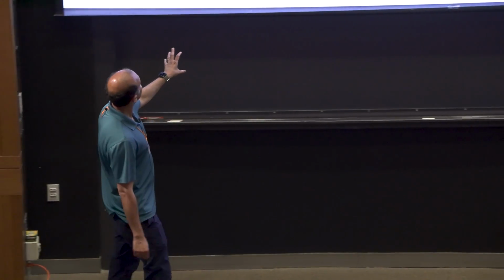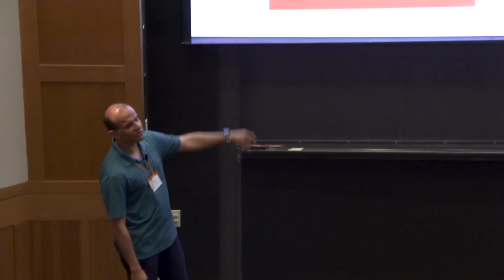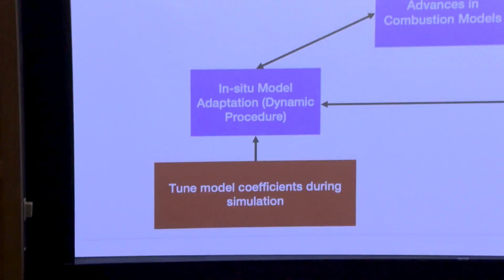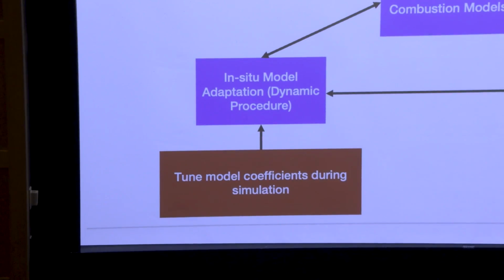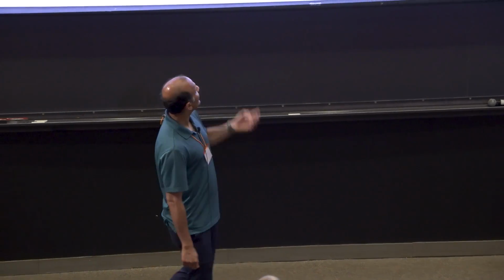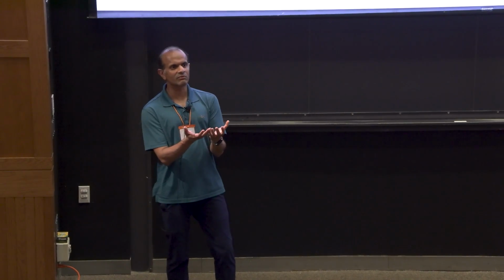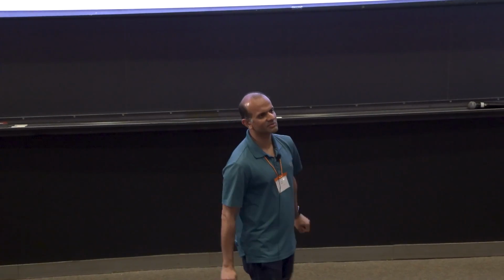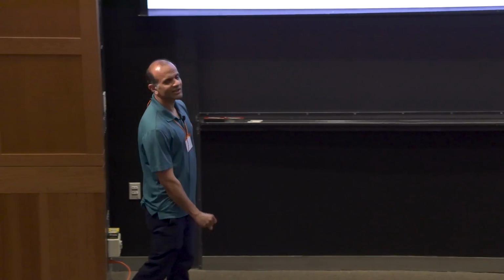Now, there's a third aspect, which is what is called in situ modeling. So this is very unique. There's only one other physics domain where you can do something like this. So LES has this unique feature that you can build the models from within the simulation itself. So you don't model ahead of time, you model during the simulation, which is a very unique concept. I haven't seen this elsewhere, until, of course, machine learning came by. I haven't seen this before.